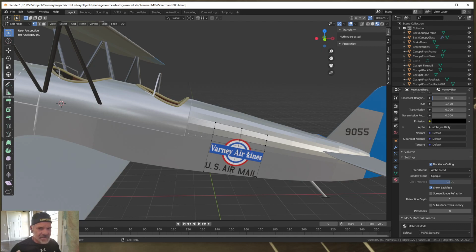Okay, the subdivision modifier on this particular model, this is scenery for Flight Simulator, so I didn't use all these subdivision modifiers. The only subdivision modifiers that I used on this Stearman is this portion up here around the cockpits of the airplane, okay, because the aluminum back in that time was bent a lot tighter. Here, this is fabric, all right, so these polygons were to look like it was going along the ribs.